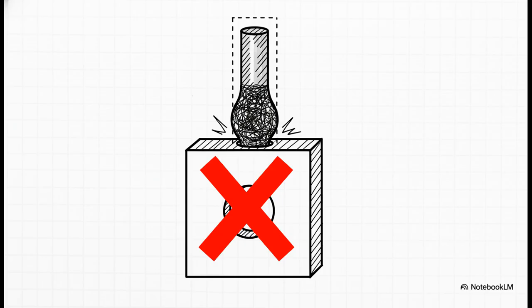If the part has any shape variations at all, like poor straightness or bad roundness, that cause the cylinder surface to bulge outside that 25.1 millimeter virtual boundary, it simply isn't going to assemble. Think about it. Even if your calipers are telling you the diameter is totally fine, an out-of-round, potato-shaped shaft is going to push right past that boundary and fail assembly.